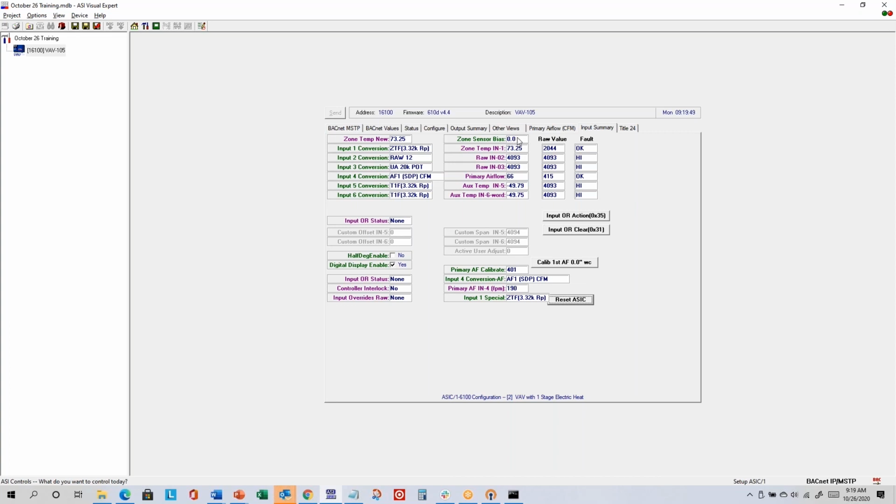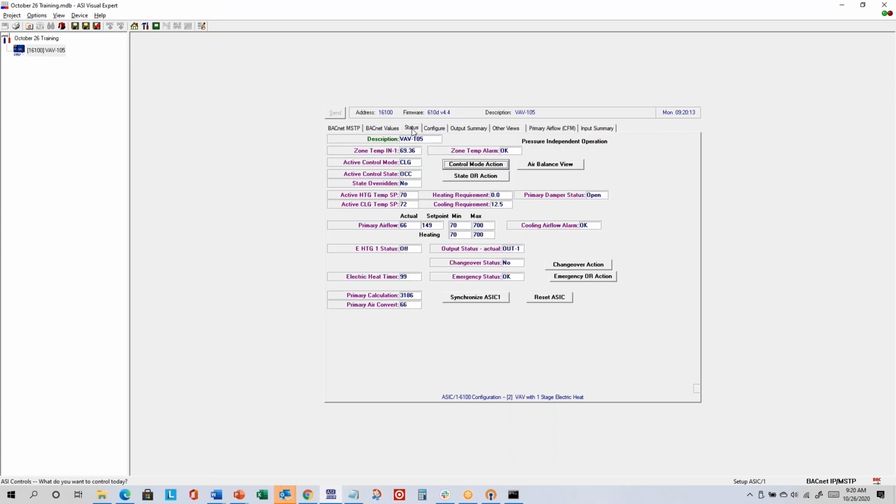And it probably has a 0.0 value in right now. If you click on that, it shows you can enter a value between the min value of -10 and the max value of +10. So I'll put in -4. And then my zone temperature will go down by about 4 degrees, which should be lower than my 70-degree set point. And it is.